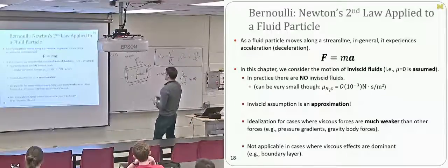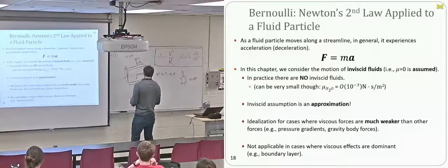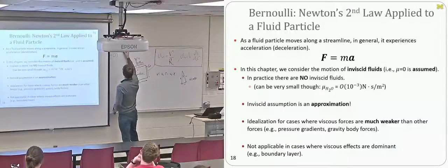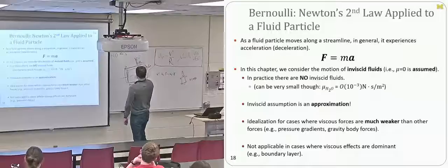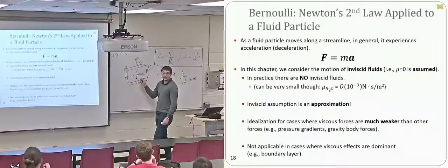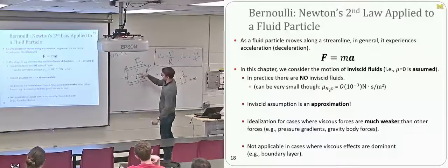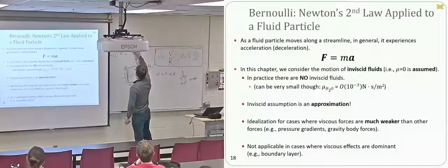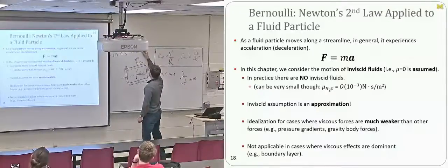So let me find somewhere to put our sum of the forces. So there's weight. Let me move our sum of the forces up here. Sum of the forces in the S direction equal to, is that going to be positive or negative? The weight. Negative, yep. It's acting this direction to sort of push the fluid particle back downhill. So we've got W sine theta now plus